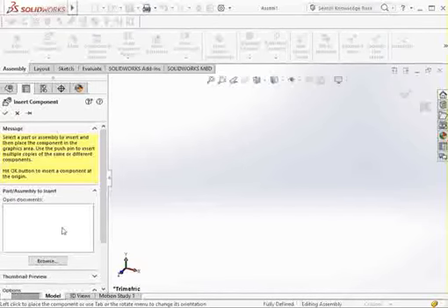When you come here, you see that there is nothing here. For some of you who are going to be working that day, after drawing the parts, you may just press Ctrl N on your keyboard and that will open a new part. You are not going to close the window for the part that you have designed.